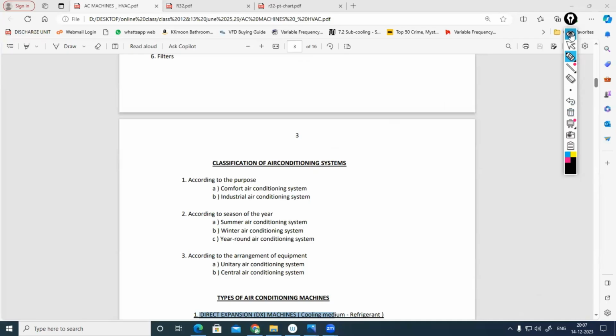Excuse me, sir. Where do we install this CO2 sensor and this temperature and RH sensor? Carbon dioxide sensors are in exhaust ventilation systems only. For example, if you have a car park exhaust system, normally it will be calculated at 6 air changes per hour, and with the fire consideration, we will consider 10 air changes per hour. So the fan will be selected with 2 different speeds. Normally the fan will work for 6 air changes per hour, otherwise it will work for 10.